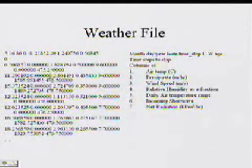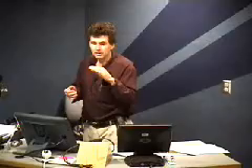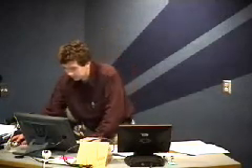Now, the model is set up so you actually have to give numbers here, and then you can tell it whether to use the incoming shortwave or to use the net radiation, or to just assume that that data is not available and calculate the shortwave radiation based on the daily temperature range. But numbers still need to be in the column. If you don't have the numbers, you can just put zeros or anything you like there, and the model will not use it if you tell it to use the option that doesn't require them to be used.